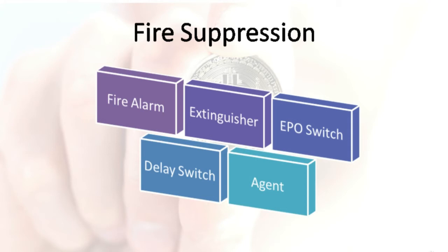The detection system is intended to determine whether a real fire has begun or just a false trip. And to prevent false alarms, the detection system should detect both smoke and heat. As for the fire alarm itself, it is to signal appropriately that everyone needs to evacuate. So this should include both sound as well as visual signals, such as blinking lights. This should usually be described within the required building codes. So the look and feel of the fire alarm is basically defined by whatever is set up regionally in your